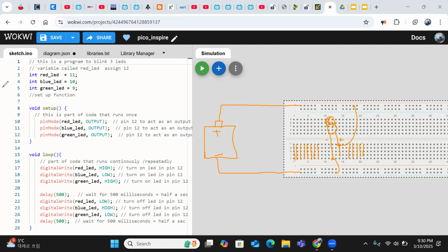I have a question. The positive of the LED is on a different vertical line. So if the LED comes here, the positive comes here. Do you see that? Yes. You see this one, and even this upper one, this one, and this one? They are all connected. So you can use any of them, even that one, and then you take it to the positive.